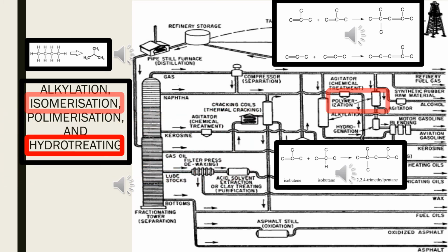It also is not indicated on the diagram, but if you need to remove sulfur from crude oil, you can consider hydrotreating, which is mixing it with hydrogen, heating up to 300 to 380 degrees centigrade, and then feeding to a hydrotreating reactor loaded with a catalyst.